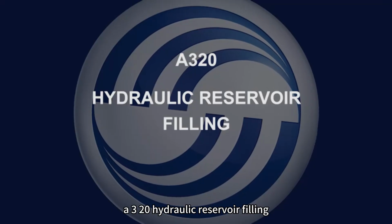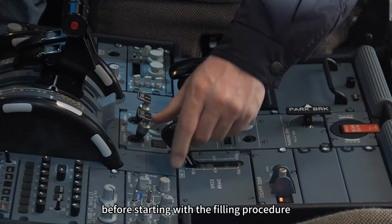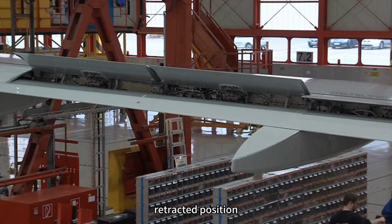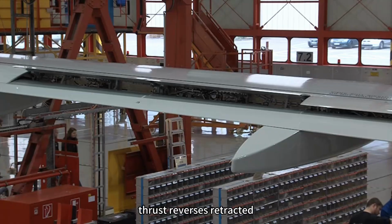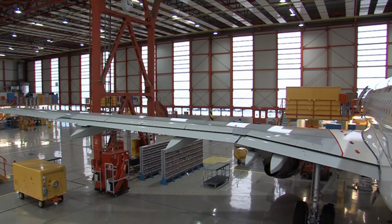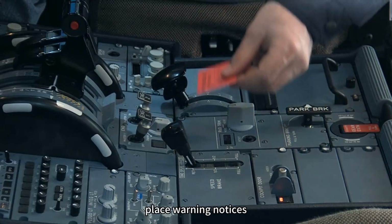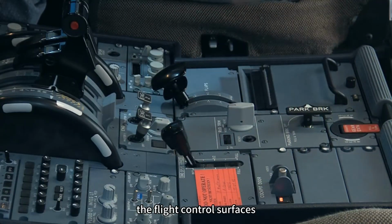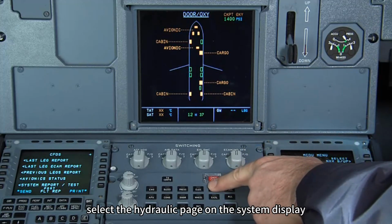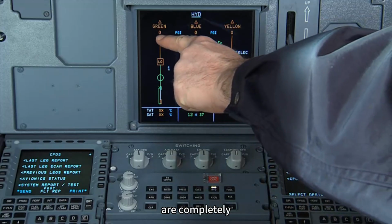A320 hydraulic reservoir filling. Before starting with the filling procedure, all flight control surfaces must be in their neutral retracted position. Thrust reversers retracted, and the cargo doors must be in the closed position. When the flight control surfaces are retracted, place warning notices to prevent others from moving the flight control surfaces. Select the hydraulic page on the system display and make sure that the hydraulic systems are completely depressurized.